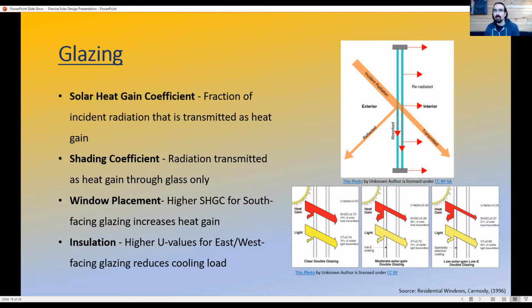And the way that the windows are rated for their insulation value is the U value. That's the inverse of the R value. We want to have a lower U value for your east and west facing glass that's going to have a lot more direct sunlight in the early morning and in the late evening. But then it's also something that's important to consider for your south facing windows, because as I said, if we have a third to 2/3 of our entire wall square footage made up by glazing, that's a large amount of area that has a very low insulation level. So if you did end up designing a house that was all windows on your south side, that entire side of the house may have an R rating of less than 4.